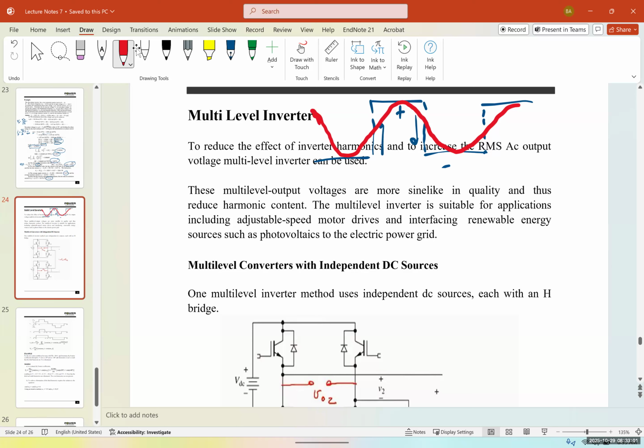And the limitation for this, as mentioned, we can solve it using some filters. That's a good way. Another way was to use different conduction modes and to use pulse width modulation for that. But a different approach is, instead of having just two stages of signal being on and off, what if I divide that input voltage into multi-levels? Imagine if I put that 220 voltage into a voltage divider, then I have 120 volts. Now I have one stage that is 120 volts. Then I have another one that is 220 volts, for example.